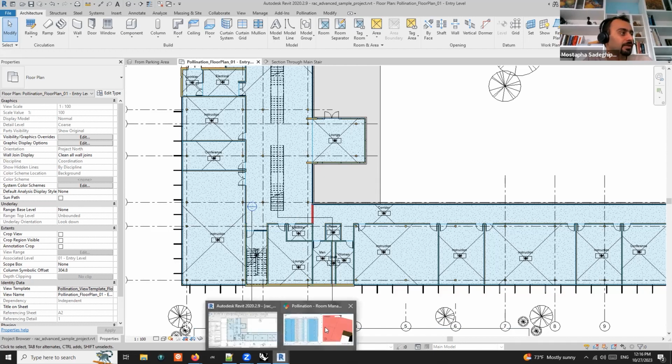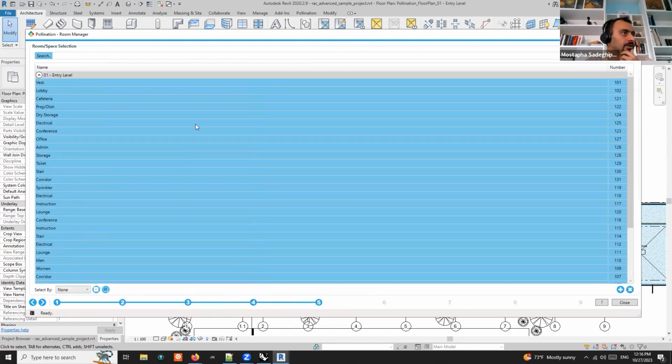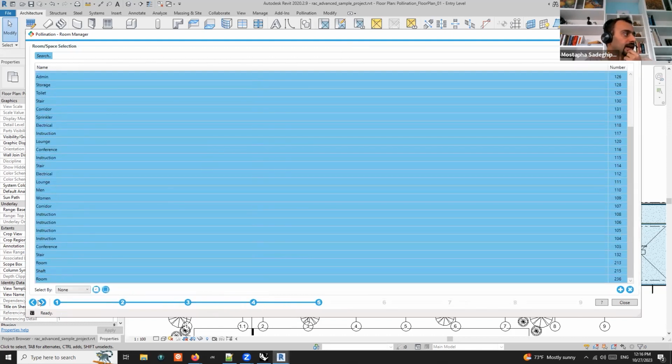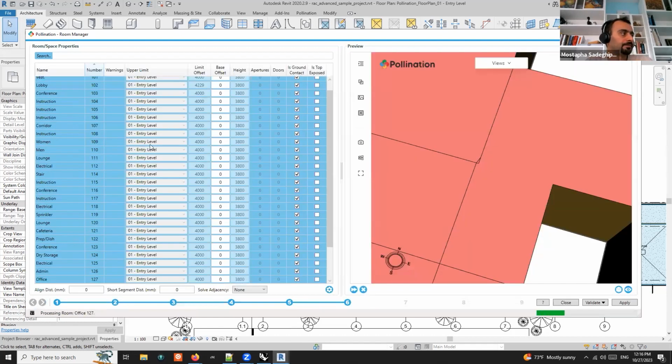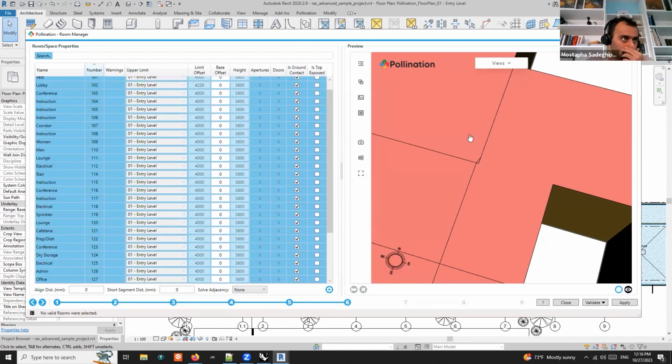So yeah, I removed those room bounding things. And now if I go here, I can set the remove short segment to 0, right? Go back to step 5 or 4. I think it's 5. So I make sure it loads all those new rooms that I added. Come back here, and it parses everything. And now look at the model. It should look okay. And if we run the validate command, everything should run fine. Any questions so far?